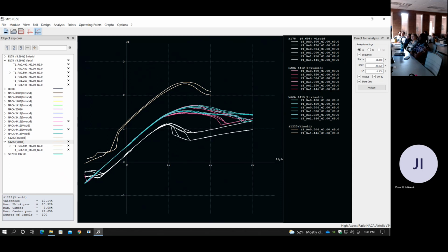So it depends upon your application. If you need to take off really quickly, or you have a high takeoff weight, then you might want to consider a high cambered airfoil. You don't have to pitch up to fly, but it comes with huge drag always when you're flying. That's what the high cambered airfoil is.